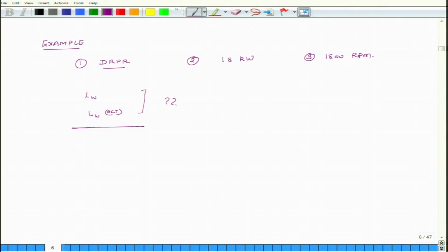If this is the information, then we first figure out the sound power level, which is A weighted, and the relation for that is LWA equals 20 log 10 of the power of the motor expressed in horsepowers plus 15 log 10 of the RPM minus 3.